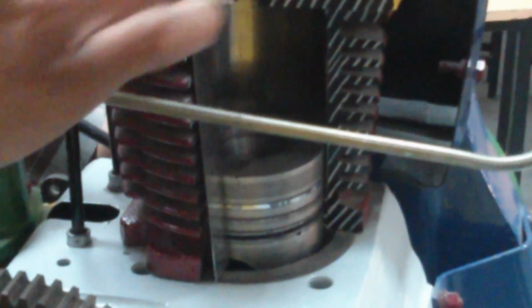So when you want to mark the valve opening, we are just rotating. When I am rotating, when this just begins to move down, when you just notice the movement, that point I mark as the inlet valve opening. Now you can see that here this compression is happening. Now as the piston is coming downwards, right, my inlet valve is opening. Now the suction stroke is happening.